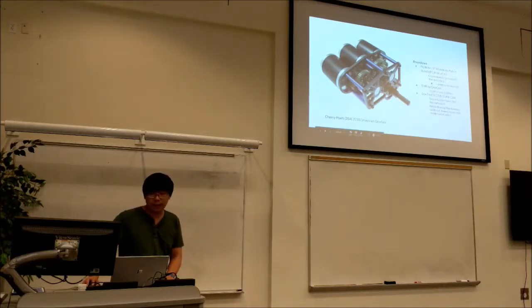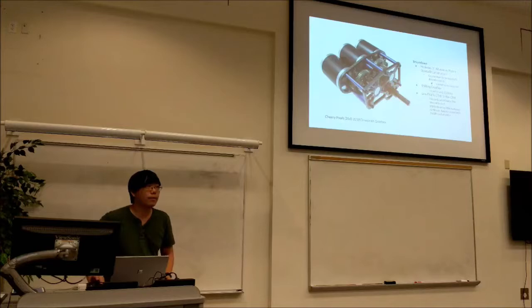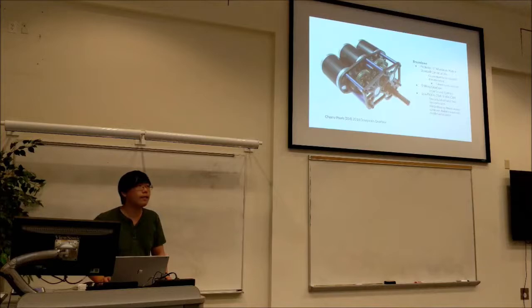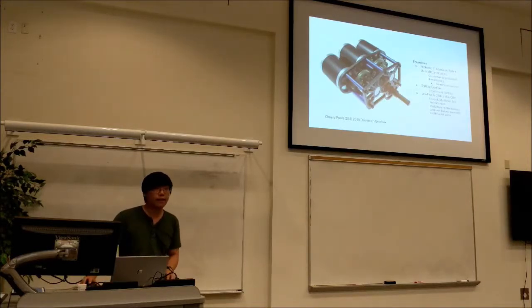Also in their gearbox, they have two sizes of standoffs. On the bottom, they have a larger standoff, and that actually has a counterbore in the plate. That adds rigidity to the custom gearbox, but we didn't use any counterbores last year, and we found that was fine. And there's a benefit to not using that, because in Georgia, we get access to water jets, and you can't do a counterbore on a water jet. So you don't necessarily need to use it, but it is an option. And then this particular gearbox is a shifting gearbox, so that they were able to achieve 2 speeds.